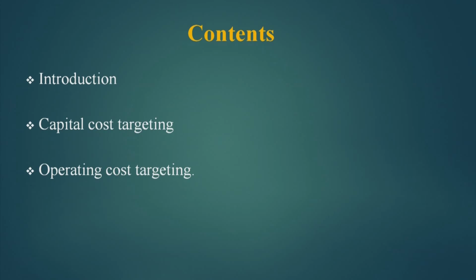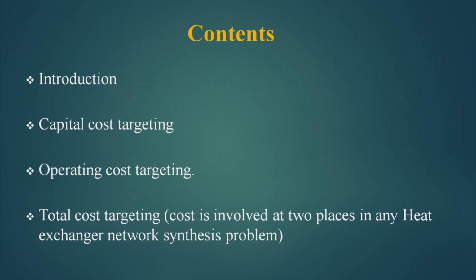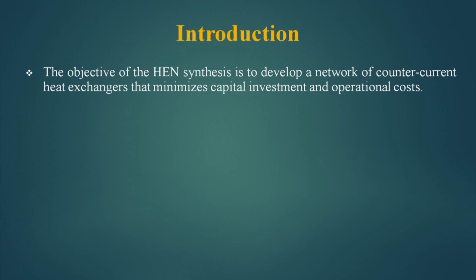In this lecture, we will introduce cost targeting, we will talk about capital cost targeting, then operating cost targeting, and finally, the total cost targeting, which involves the capital cost targeting and operating cost targeting for a HEN. The objective of the HEN synthesis is to develop a network of countercurrent heat exchangers that minimizes capital investment and operational costs.